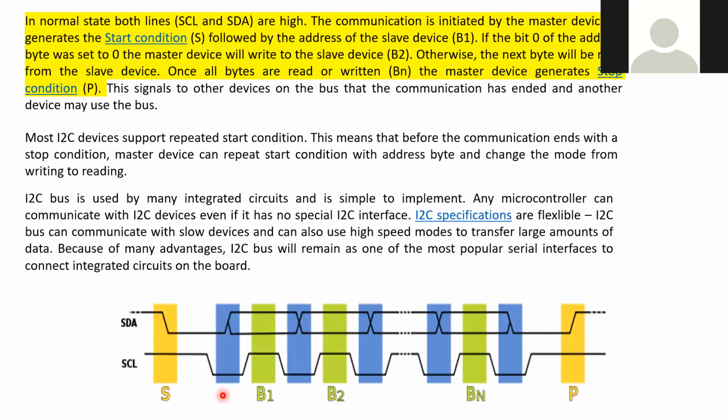Okay, now you just come to our topic, that is how I2C works. That is very, very important, because while we are saying I2C, I have a master device and so many slave devices, all the devices will be connected. So nearly 128 devices are connected, but I have to identify each one. Just as you have a roll number or register number to identify you as a person, in a similar way, all the slave devices have an address.